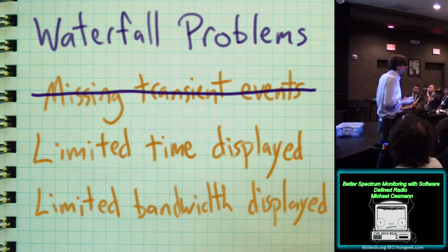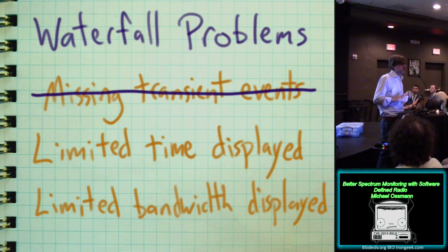These start somewhere in the tens of thousands of dollars. A real-time spectrum analyzer does exactly what GRPhosphor does. It tries to show you everything that happened during a limited window of time and frequency. And if you look under the hood of a real-time spectrum analyzer, you'll find something very similar to this. It is simply a high-end SDR platform with software on the front of it that is similar to GRPhosphor.